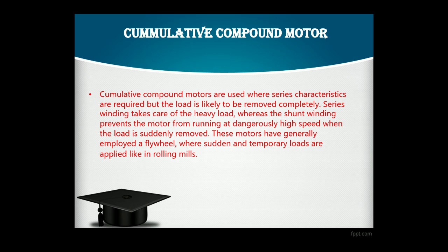These motors generally employ a flywheel where sudden and temporary loads are applied, like in a rolling mill. In a rolling mill, the load is sometimes higher and sometimes very low, so the cumulative compound motor is used.